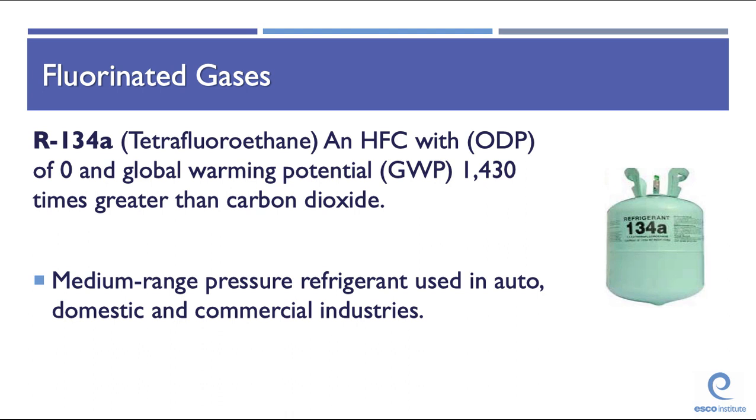R134A is an HFC with an ODP of 0 and a global warming potential 1,430 times greater than carbon dioxide. R134A is a medium range pressure refrigerant. It's used in auto, domestic refrigeration, and commercial industries. You'll always recognize it because it's in this sort of light green cylinder.